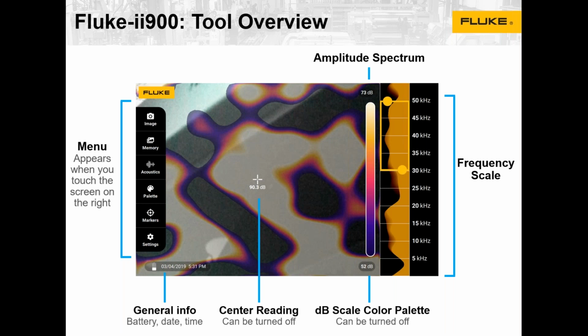So if you press and just put your finger on the touch screen and hold in the middle of that rectangle and slide your finger up and down, it will essentially allow you to eliminate the sounds happening in frequencies outside of the band that you've defined. So say, for instance, you're in a really noisy facility and you're getting a lot of noise in the 5 to 25 kilohertz range. And you know that the compressed air, compressed gas, or whatever type of leak that you're looking for is going to have a sound profile in those higher frequencies, you can adjust that band and scale it up to only visualize sound in those higher frequencies, similar to what's being done on the example here on the screen. So it allows you to not only hear things that you can't hear with your ear, but to eliminate a lot of the other sound happening in a facility.